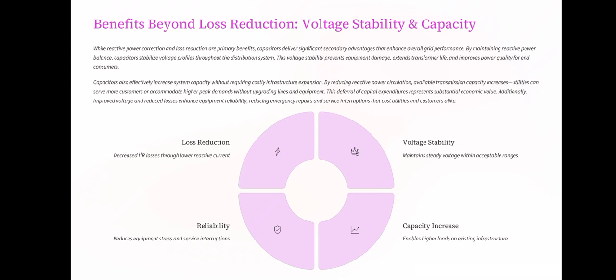Capacitors also effectively increase system capacity without requiring expensive infrastructure. By reducing reactive power circulation, available transmission capacity increases. Utilities can serve more consumers and accommodate higher peak demands without upgrading lines and equipment. This deferral of capital expenditure represents substantial economic value.